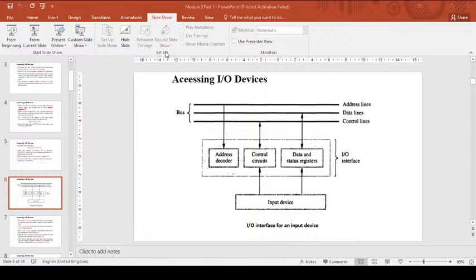So what does it do? Again the repetition. You have studied this similar program under program-controlled IO: reading a line of characters through the keyboard and displaying it, using a memory-controlled IO operation. So what happens here? Move #LINE, R0. So LINE is the address.